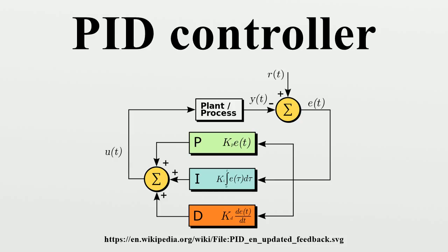The use of the PID algorithm does not guarantee optimal control of the system or even its stability. Some applications may require using only one or two terms to provide the appropriate system control. This is achieved by setting the other parameters to 0.